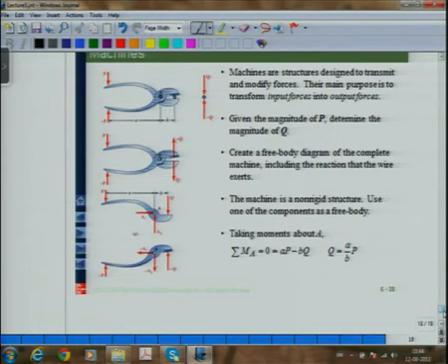So now when I draw the free body diagram of this link, I have the force F here, there is a pin at A. So at the pin I will get AX and AY as two unknowns, and if it is given it's frictionless, which it is given in this problem, then at Q you will get only a vertical force. So given P, you have to find Q. What is the easiest way? Take moments about A is equal to 0. So you will get P multiplied by this distance must be equal to Q multiplied by B. So you will get the force at Q.